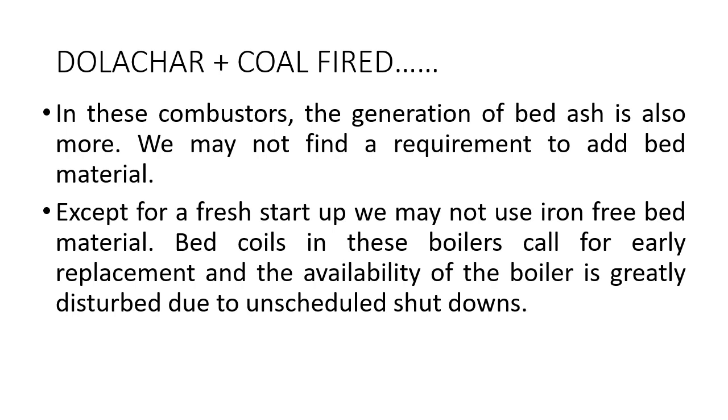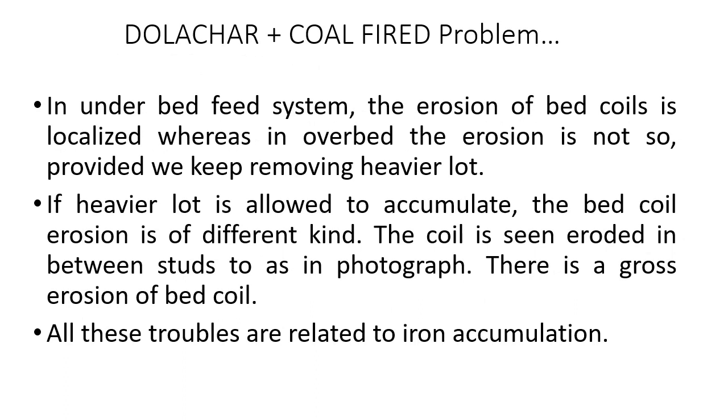In underbed system, the erosion of bed coils is localized, whereas in overbed the erosion is not so, provided we keep removing the heavier lot. If the heavier lot is allowed to accumulate, the bed coil erosion is of a different kind. The coil is seen eroded in between the studs too, as in the photograph. There is a gross erosion of bed coil. All these troubles are related to iron accumulation.